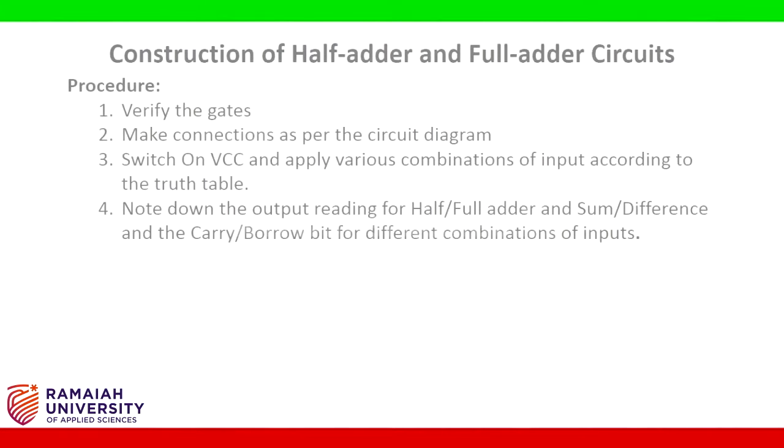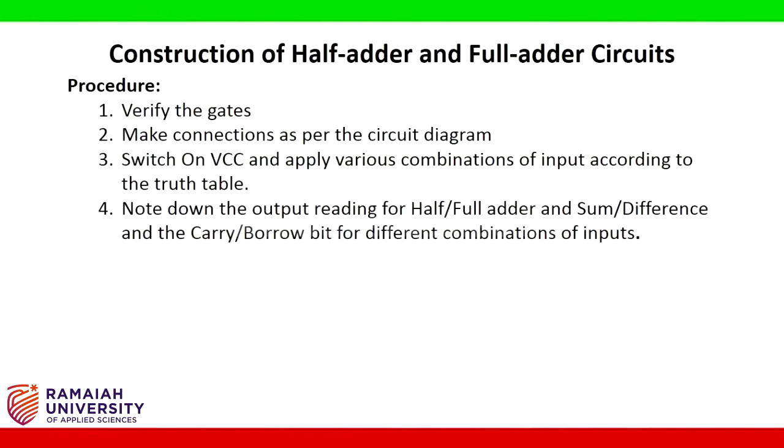Procedure for verification of adders. Verify the gates. Make connections as per the circuit diagram. Switch on VCC and apply various combinations of input according to the truth table. Note down the output reading for half adder, full adder, sum and difference, and the carry and borrow bit for different combinations of inputs.